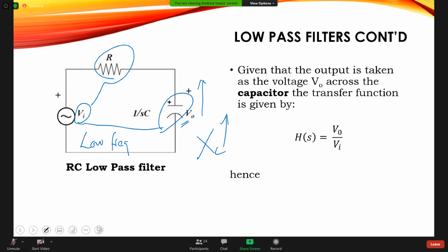Now, if you think about it, and if you go back to what you were doing in high school, or possibly you may have done it in electronics here, one of the simplest filter circuits after you have done the rectification is just to throw a capacitor across the output. One explanation is that it's used to shunt, to create a short circuit for high frequency signals. Okay? And so you'll get the lower frequency. So it will be coming closer to DC.